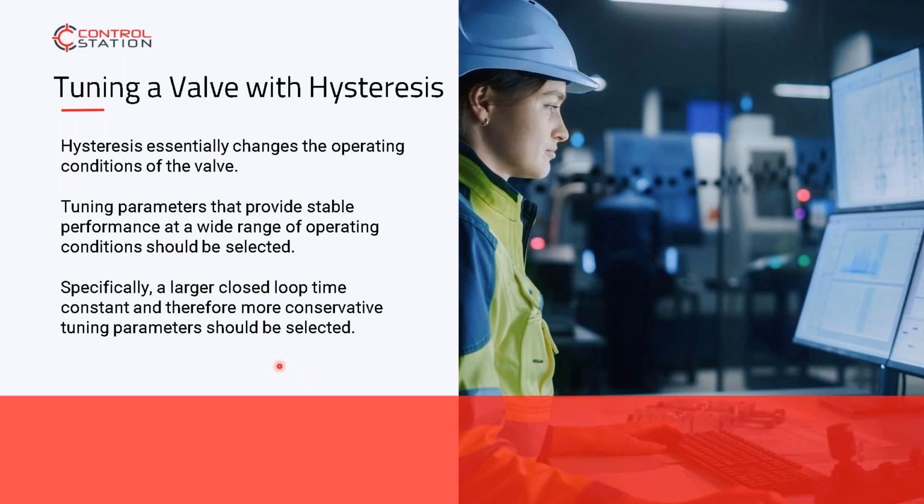If you've defined that it's a stiction problem, slow down your integral. If you've defined it's a deadband problem, slow down your integral. If you've defined it's a hysteresis problem, be more conservative. You can do that with both the proportional and the integral. You can decide to step back on that. Now, you're changing your tuning parameters, but you're not changing them for a good reason. You're changing them because you cannot get at the mechanicals. You cannot change the hysteresis on this until we upgrade the process next year. You cannot get at the packing of this valve because we don't have a shutdown for another 3 months.